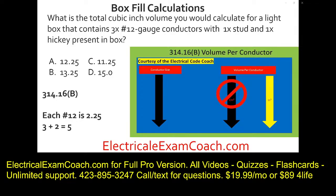Our code states that for each stud and each hickey, they count as one each based off the largest conductor that's in the box. In this case, we only have number 12s, so they're going to be grouped with the 12s. So that lets us know that we have a total of 5 number 12s. That's what I meant by we're converting everything back to conductors, and then we can do our multiplication. We take those 5 number 12s, multiply it by the cubic inch volume for 12, and we end up with 11.25 cubic inches, and we would select C.